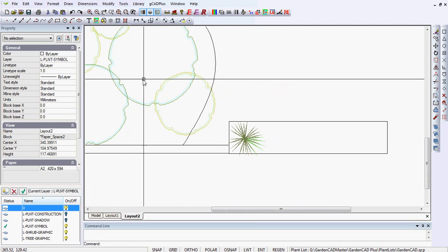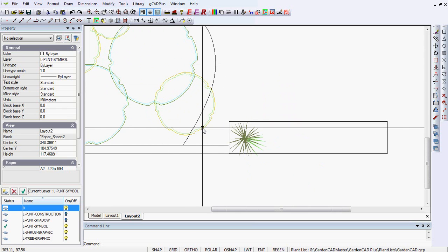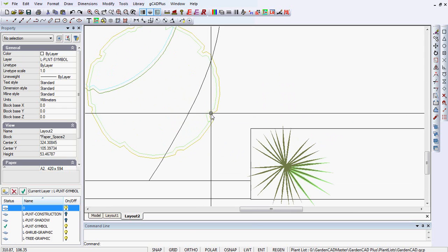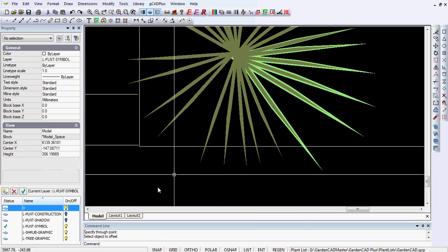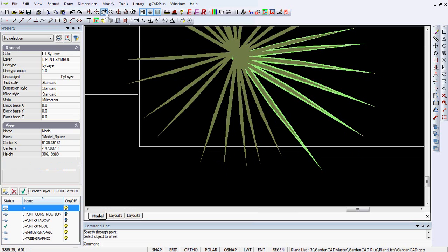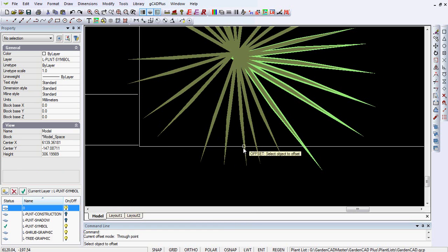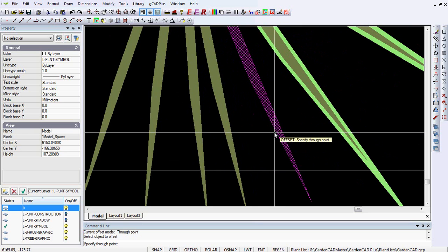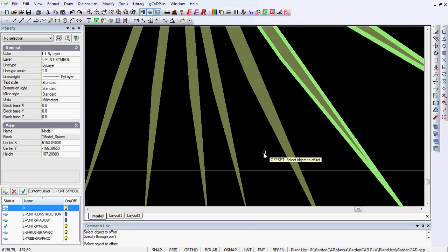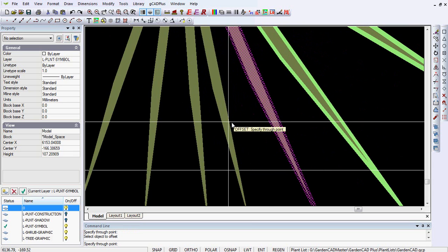We've done the same with the tall shrubs and the tall trees rather, and the medium shrubs. So I'm picking up just that same little light cyan color. So if we come back here, what we're going to do is use Modify and the Offset command. I'm then going to pick the polyline, come in quite close to the polyline and just offset it. And if I then select that new polyline, you can see it's slightly thicker than the original.